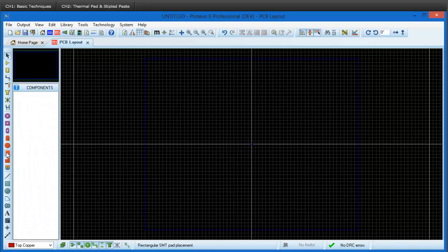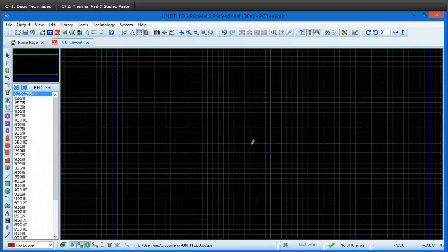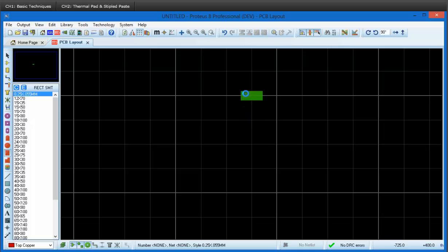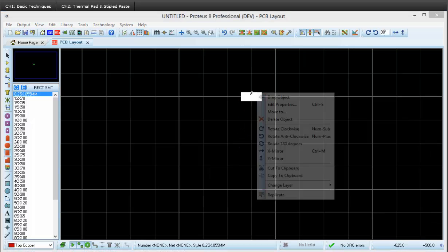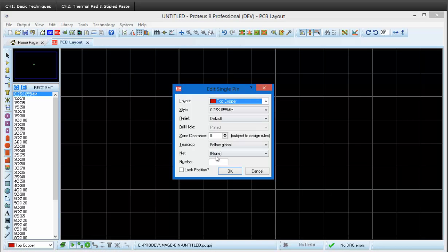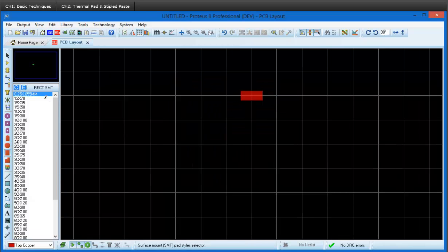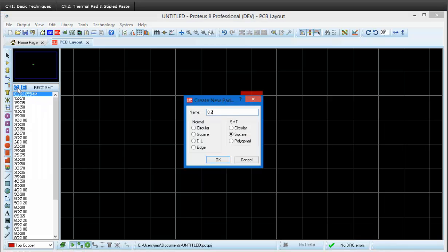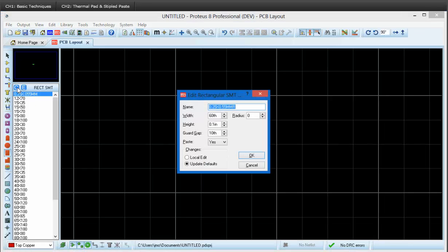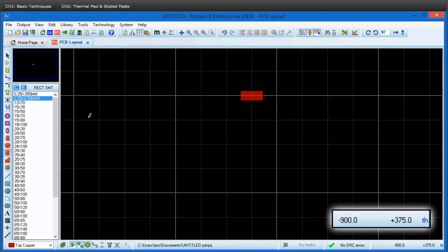The first thing to do is place the pads. Pins are 0.25mm by 0.55mm and we can place pin 1 directly. We want a rounded corner for the rest of the pins, so we next need to create a new pad style. The dialog form is fairly self-explanatory. We don't need a large solder resist expansion on the pads, and we set a bend radius to corner the ends. We now need to place one of the pads underneath pin 1.